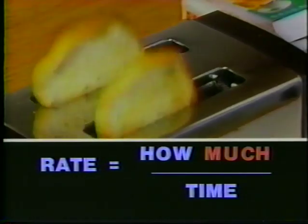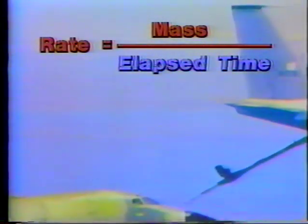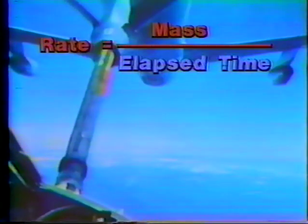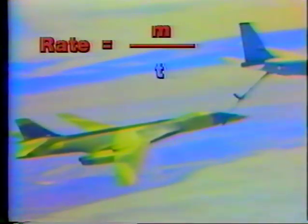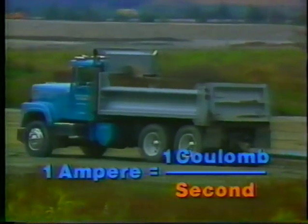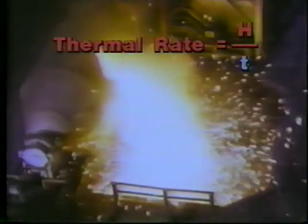When speed is not important, as in the case of fluid, electrical, and thermal systems, rate measures how much moves in a period of time. How much in a fluid system can either be how much mass moves over elapsed time, which is important in cases such as air-to-air refueling, or, as in the case of the power dam, how much volume moves over time. In electrical systems, it's very convenient that the ampere also happens to be a rate, the number of coulombs moving past a point every second.